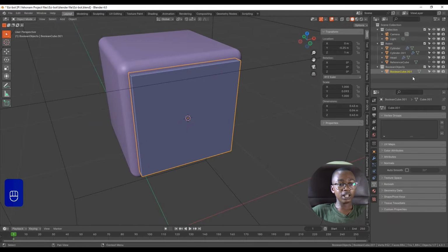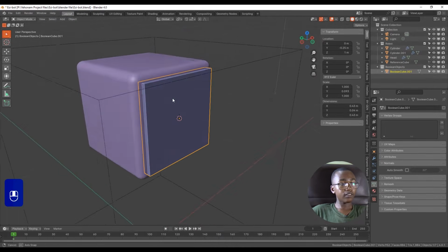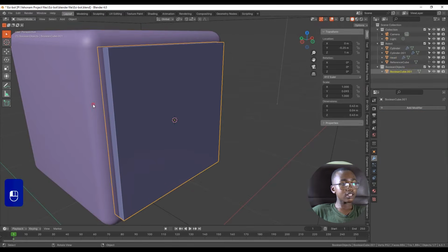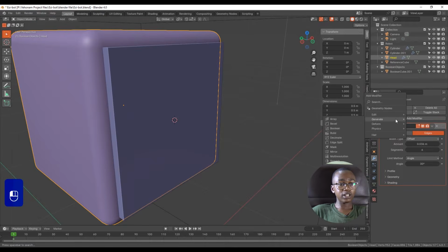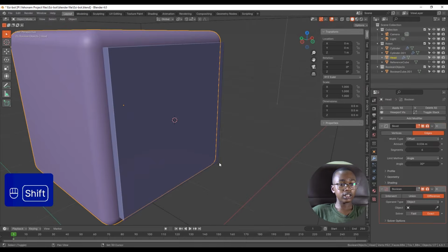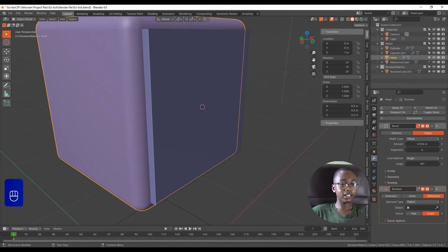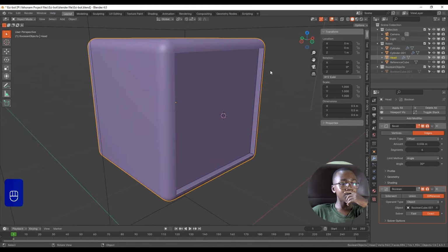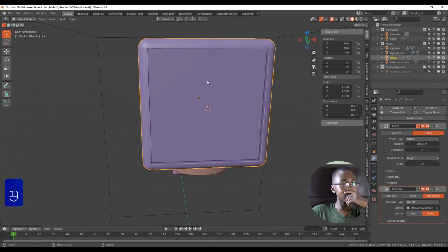And also I like to keep that tool as the mesh data name. Okay, so then to cut it, we add a Boolean modifier. So we go to add modifier, generate, Boolean. Take the eyedropper tool. I want to select this Boolean cube. Fine. Okay. So in order to see it, you have to hide it first. Then beautiful. We see that it creates a hole for us.